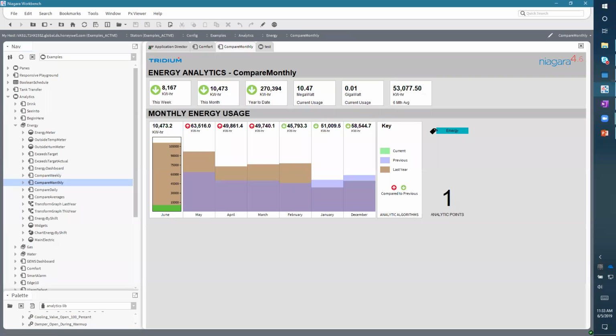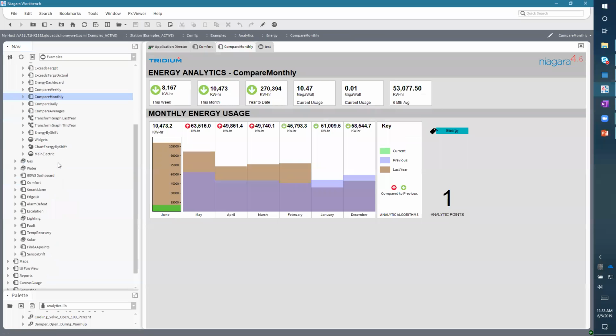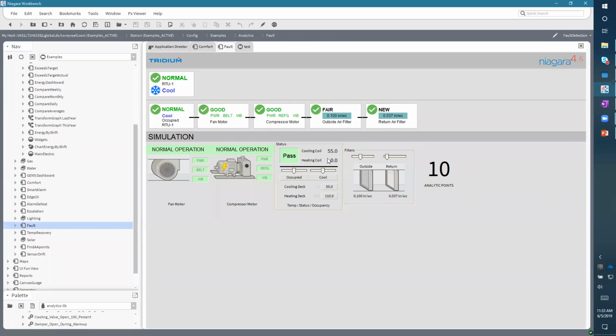Did you put together the PX graphics that you just showed for fault detection? Yes, all of these displays and components I built using algorithms that we brainstormed in the office. We said, how would I have a rooftop controller in my cube, and how would I find problems with this rooftop? So we looked at what sensors I can hook up to that controller, and we built that model based on what sensors we could add to an existing older rooftop that doesn't give us those diagnostics.